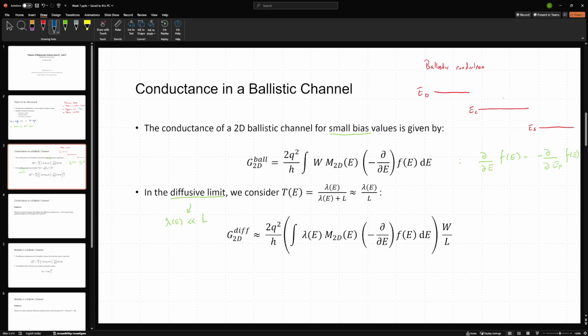So in this system, I have a first de-excitation and then a second de-excitation. What should be remembered is that the highest available ED and the lowest available ES will give me the range of energies the electrons can have. Although this integral is typically treated as an integral from 0 to infinity, it is understood that this derivative quantity here is known as the Fermi window function.